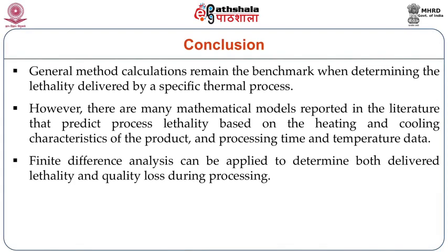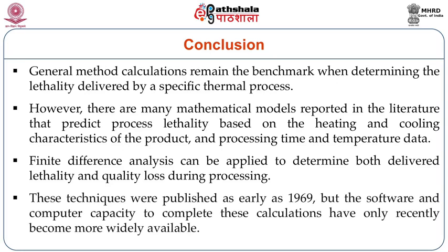Finite difference analysis can be applied to determine both delivered lethality and quality lost during heat processing. These techniques were actually published much before 1969, but currently we have many advanced techniques and software, and computers also have the capacity to complete these calculations, and you can apply them for various methods of processing.